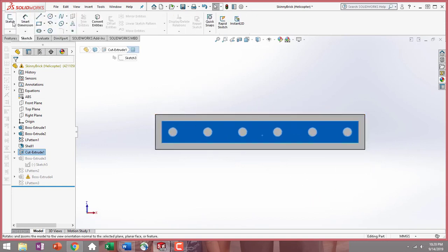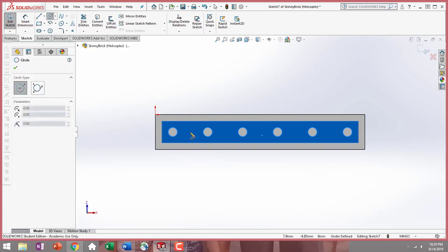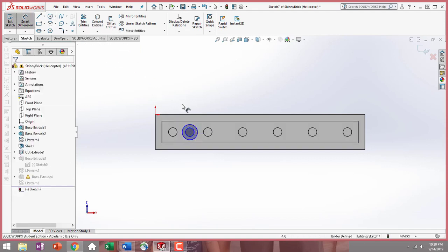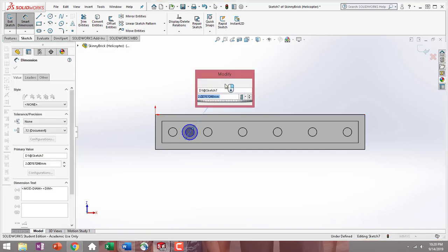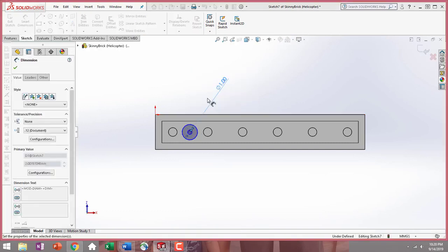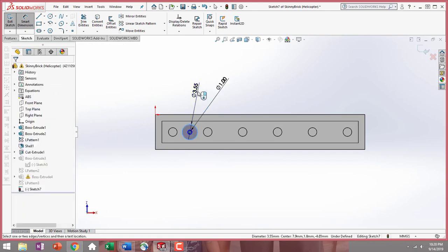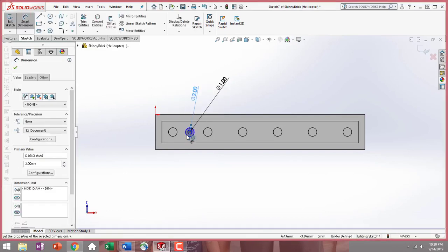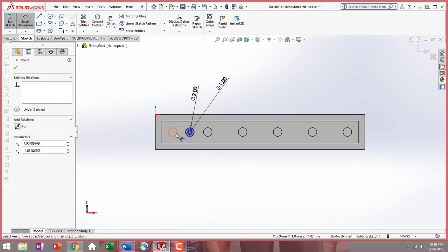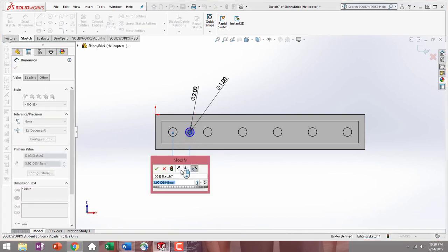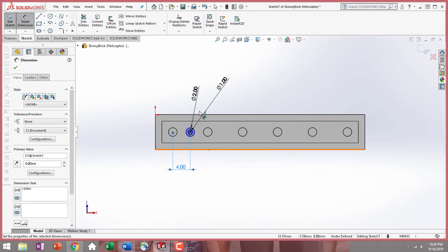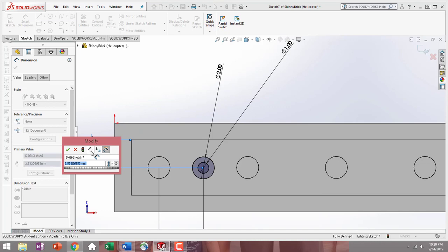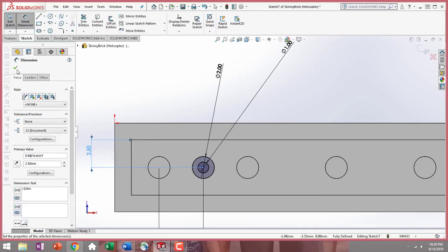Go to the Sketch tab, open up a new sketch, and create 2 more circles within themselves if you are creating a new one. You do not have to. I'm going to move a little faster on this since we just did it. Remember to dimension that inner circle 1, our outer circle 2, dimension of 4 in between, then a dimension of 2.5 to center it.